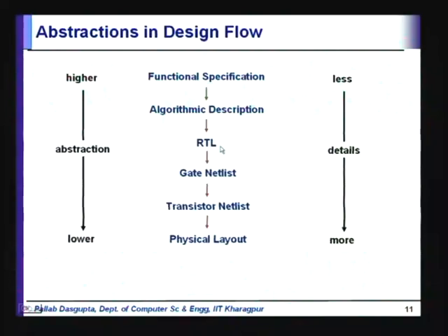When you are sure that this is all right, then you start writing the RTL. Now, the interesting thing is that today mostly the arrow that you see here between algorithmic description and RTL is manual. After all that modeling, all you have done is check whether your architecture is implementable, but then you start writing the RTL code again by hand. And that again is a source of bugs, because the RTL designer may not interpret the architectural specifications in the correct way.